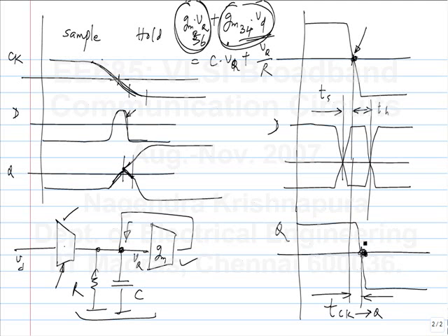So if you look at the zero crossing point, M5 and M6 don't affect it. What M5 and M6 do affect is whether it comes out like this or like this. Size of M1 and M2 will affect, yeah, actually everything affects everything in that way. M1 and M2 are crucial to everything. If they don't switch completely, then the input is always contributing to the output and the positive feedback latch is always active to some extent. So M1 and M2 will contribute to everything.